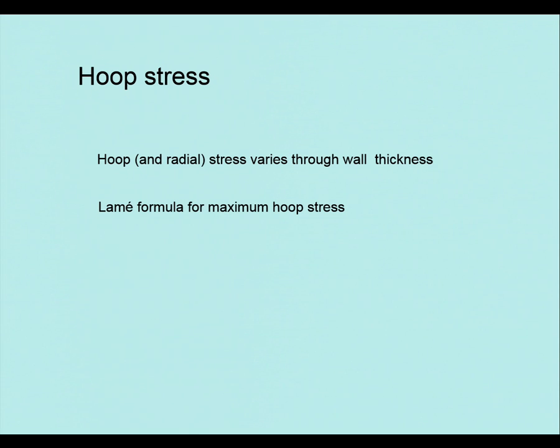So in that respect, with the thick wall, like here, if this is drawn thick, the hoop stress will vary from inside to outside. What you've done in the other Barlow formula with the thin wall is assume that the hoop stress is constant straight through the section.